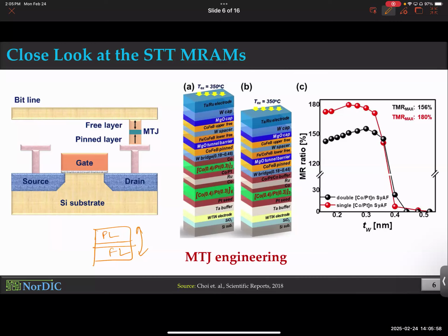And I mean, since you asked, actually, I'm almost tempted to add one extra bit of information here. Oftentimes, in recent research, there is a surge in interest towards making MTJs that have multiple levels, which I didn't tell you about. We talked about AP and P MTJ, anti-parallel and parallel MTJ, which had high resistance, low resistance, just two levels, so that you could represent 0 and 1.